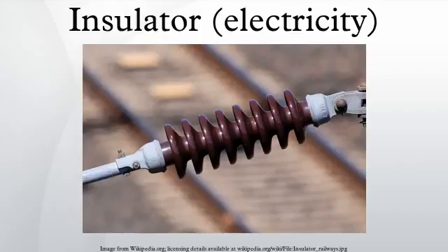To accomplish this, the surface is molded into a series of corrugations or concentric disc shapes. These usually include one or more sheds, downward-facing cup-shaped surfaces that act as umbrellas to ensure that the part of the surface leakage path under the cup stays dry in wet weather. Minimum creepage distances are 20–25 mm per kilovolt, but must be increased in high pollution or airborne sea salt areas.